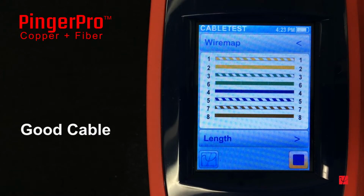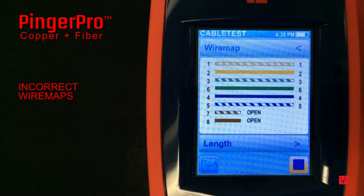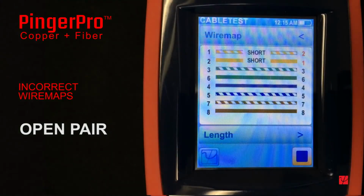When terminating an end of a network cable, it is easy to miswire a plug or jack, which can cause a device not to work when installed or reduce device performance due to loss or corruption of packets. Here are some examples of incorrect WIREMAPs that the PingerPro can detect. An open pair occurs when a wire is not physically connected or the cable has been damaged with one or more wires cut.